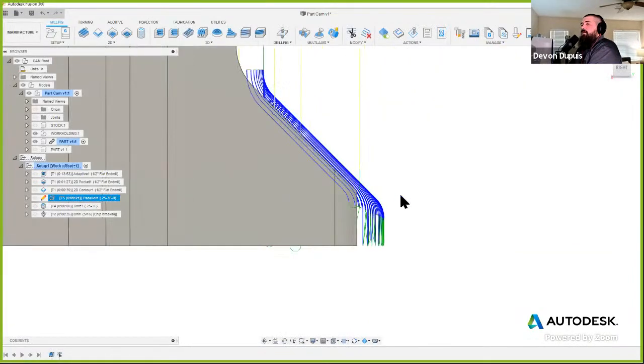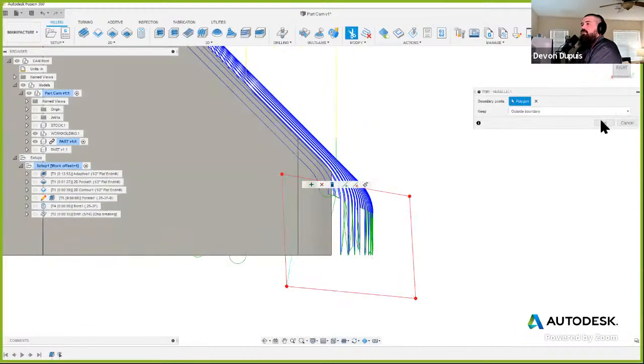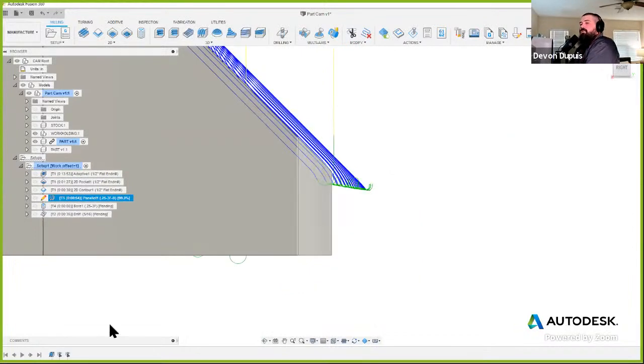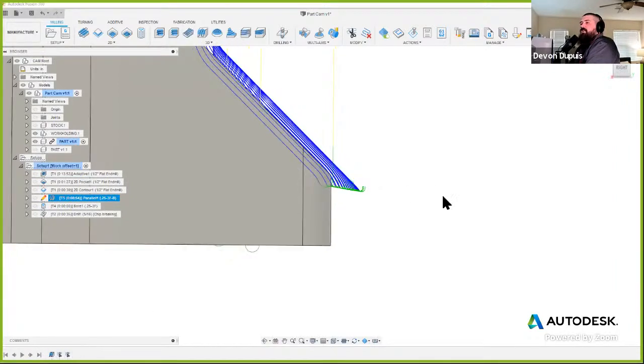But something unique about this trim toolpath is this is going to create essentially a feature in the toolpath timeline down on the bottom here. And it's going to show the edits. So you see there's a little pencil that shows that it's modified. When I click on this tool, it does show me a little toolpath timeline down here. It shows me those specific edits. So I have my 2 trims that are on here, and I can add and stack as many trims on there as I want.